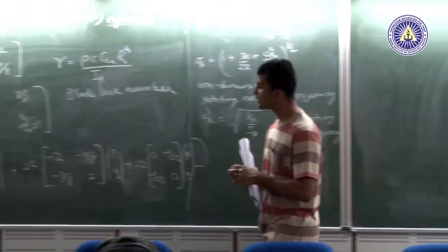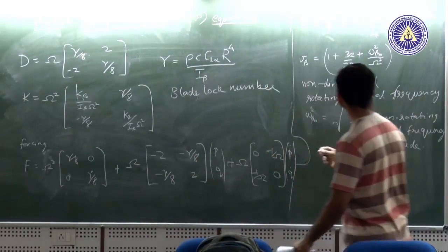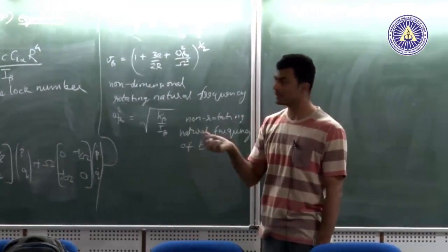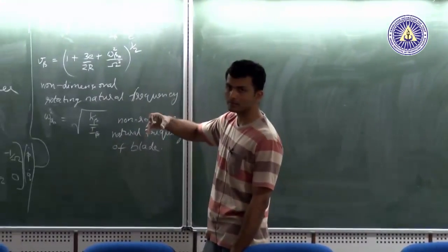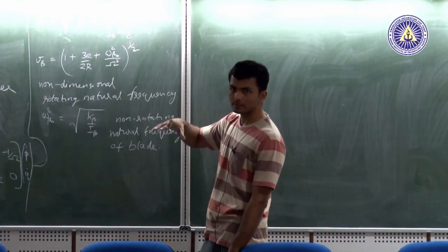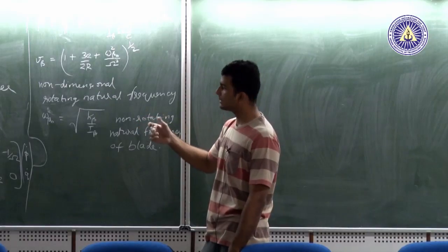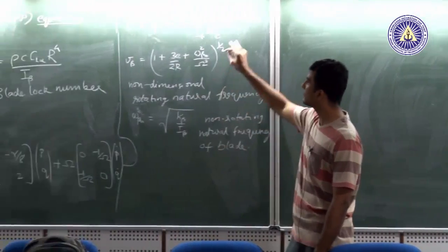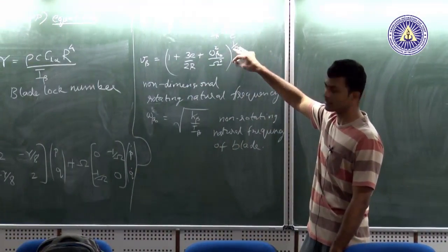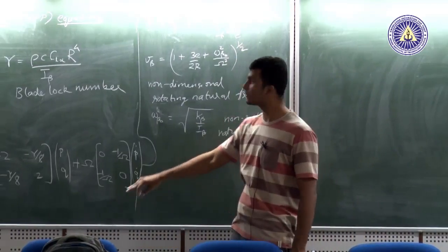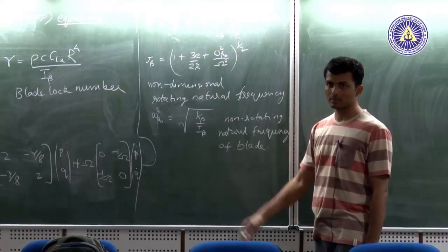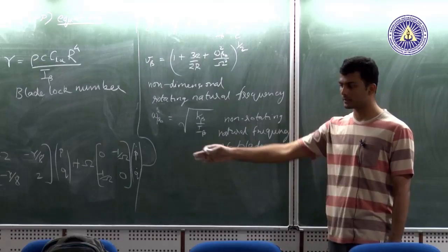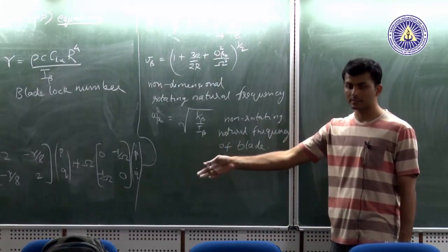If you want the equation for the forcing function, you need to express your Fz, which is the force at that elemental location I showed you previously, as a function of the angular velocity of the vehicle, the translational velocity, and the blade flap angle. Once you express it like that, you can perform the integration and you will get something like this. It will also be a function of the control input, the blade pitch angle at the two azimuthal locations, the x and y directions.